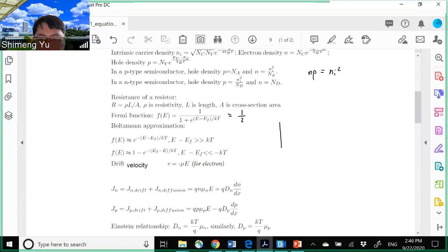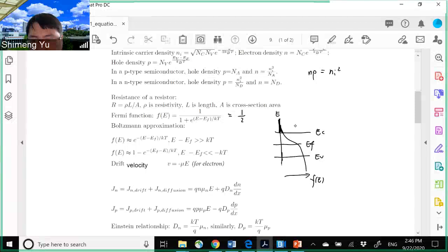This is because if you think about EC, EV, and then your Fermi function is somewhere here, this is the energy level E, and this is your EF. So this probability is like an exponential decay function toward the conduction band. Or in the p-n junction, we showed the electron distribution. You have more electrons here, fewer electrons here, and much fewer electrons here. So this is an exponential decay function. The higher the energy, exponentially fewer electrons available.